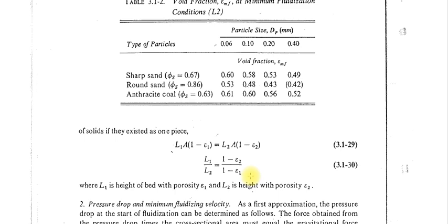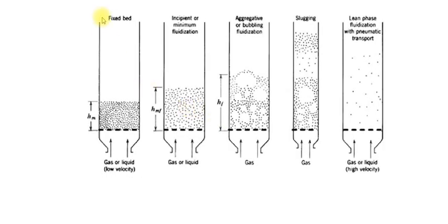If the tower is closed from the upward direction, you are in the fluidized zone only, meaning the buoyancy force is not enough to remove the particles from the tower. They are suspended only, moving upward, but not removed.